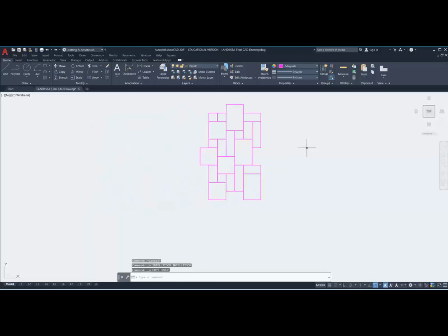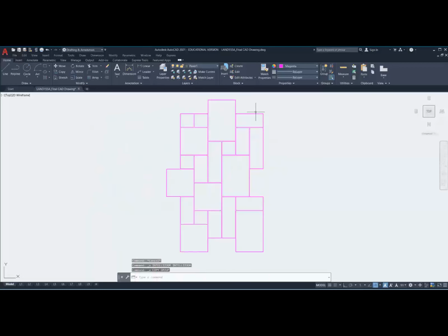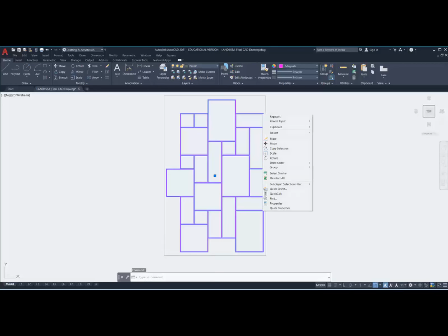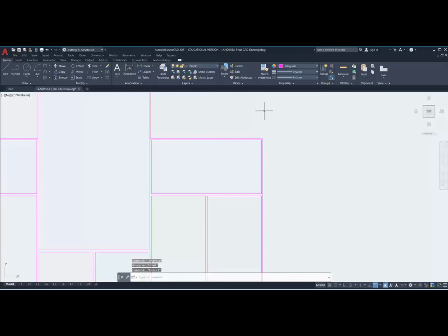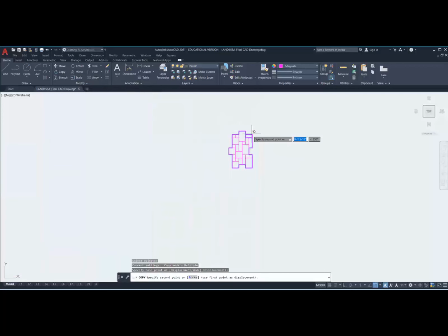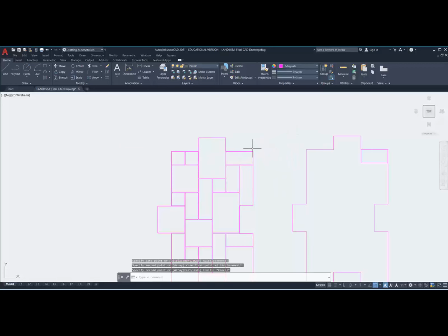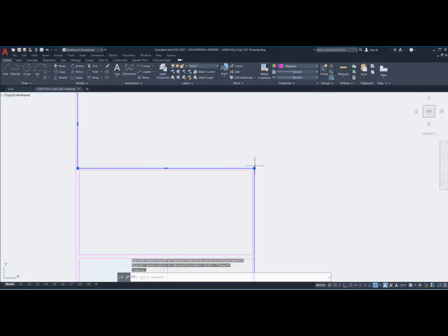Okay, so I need that reference line in the process in order to group this and to basically cut and paste it in place, but I don't want that line. So I'm going to first ungroup this. So right click on it, group, ungroup. And I'm going to copy this. And the technique I'm using is to make sure I always have a single reference from the tile for the pasting operation. And I'm putting them in separate layers, and then I'm going to turn them off.